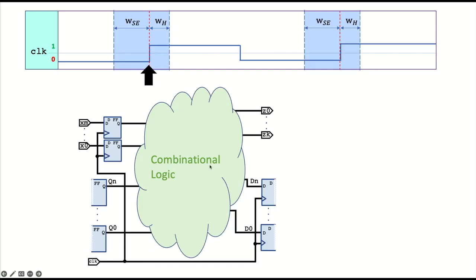Okay, so what happens is, we get a clock edge. And at the clock edge, the flip-flops will load the values and start sending them out. But this is the hold time, so we want to make sure nothing changes here. So these new values should not arrive too soon, because if they arrive too soon, then we will have violated the hold time of our flip-flops.